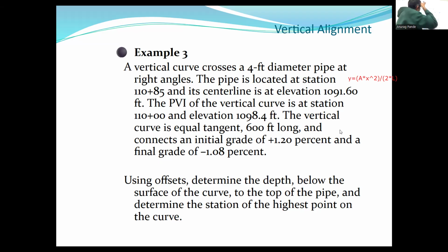And it's going to be just 1099.42 minus 2.8, right? So now this gets you 1099.42. This elevation is, we just figured out, 1099.42. You subtract from it 2.82, and then you'll get what? You will get something 0.6. I knew that. 1096.60.